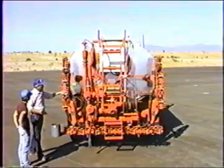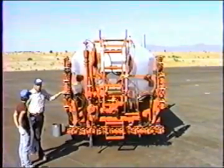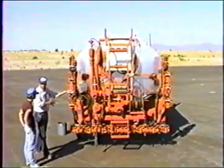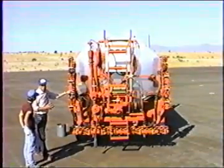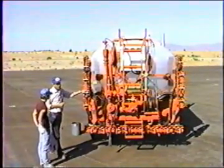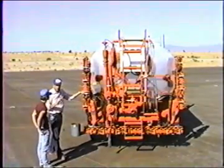Okay, there's 2 purposes for all this high-powered machinery. The first purpose is to put the asphalt down in the right place, and that's why we have control of the width, control of the side shift, wings up and down, all those sort of things. The other purpose is to put the asphalt down at the right rate. Everything that this machine does has a requirement of putting the material down at the right rate or the right thickness on the ground.